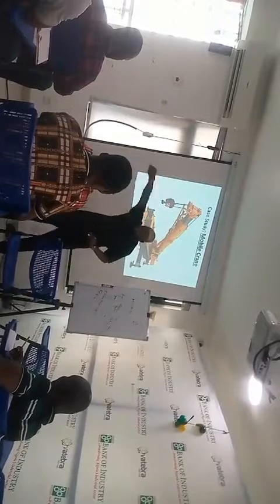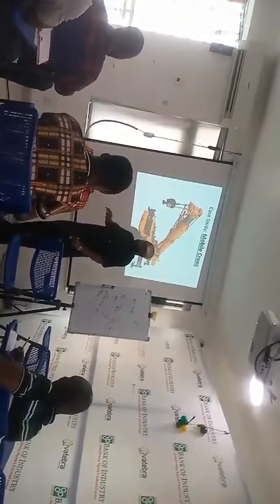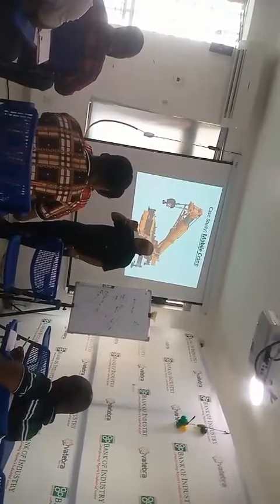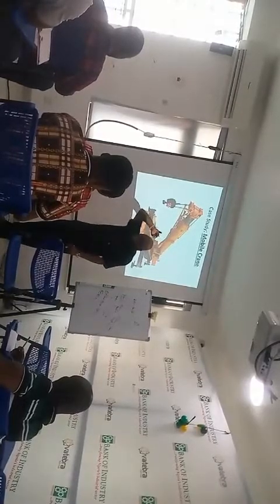They put a pole across. When the vehicle wants to pass, the space between the container and that pole they put across is what we call the headroom. So you must consider the headroom